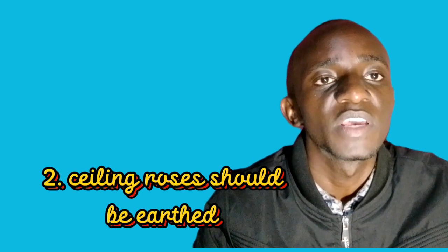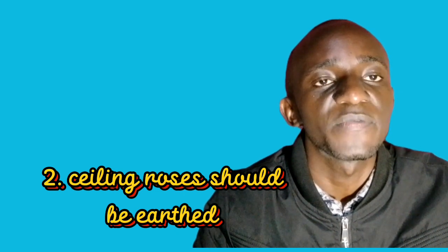The other IE regulation regarding lighting circuits is that if you are to do installation using a ceiling rose, then you should ensure that your ceiling rose is earthed. So there should be an earth conductor in your ceiling rose. Number 3,